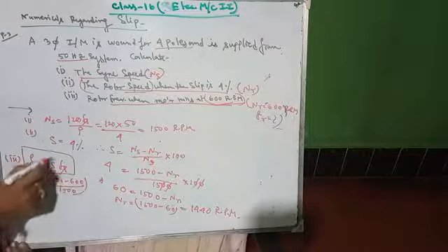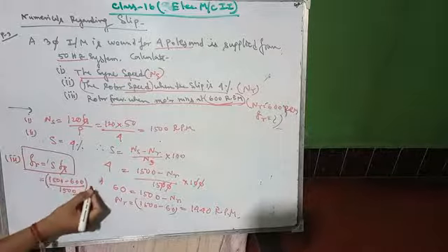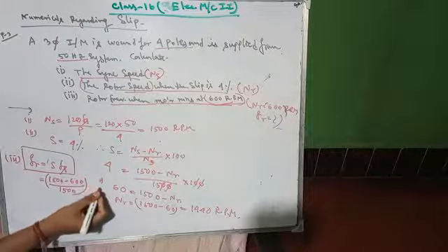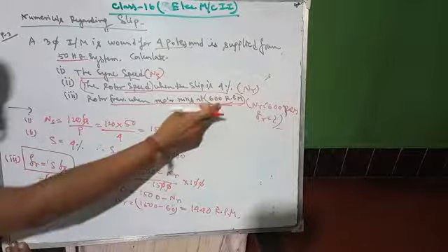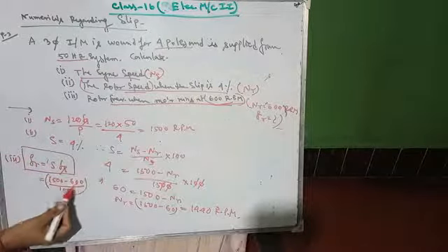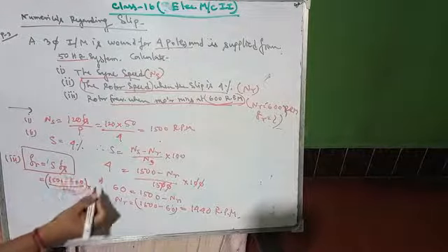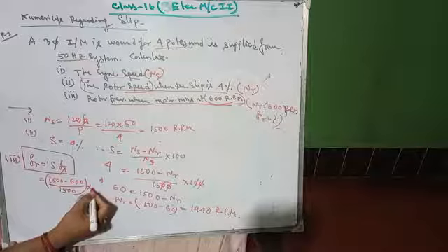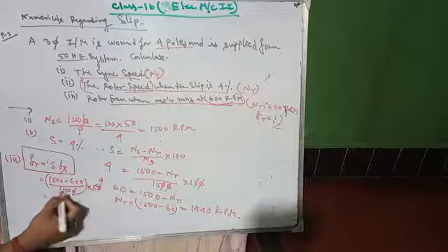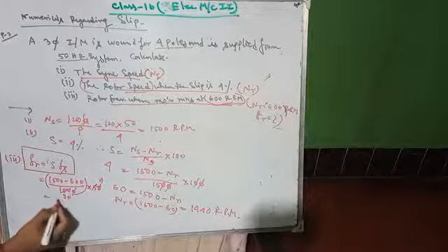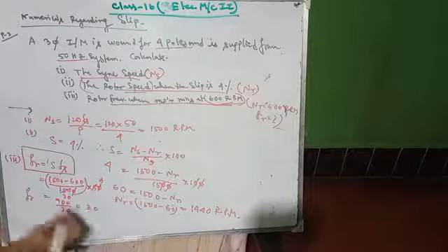Okay, so the slip is per unit, so no need to multiply by 100 here. This is your slip when the speed of the motor is 600 rpm. Ns minus Nr by Ns, that is (1500 minus 600) by 1500 into Fs, where Fs equals 50 Hz. The zeros cancel out, 5, that will be 30. So 900 by 30 equals 30. So Fr equals 30 Hz.